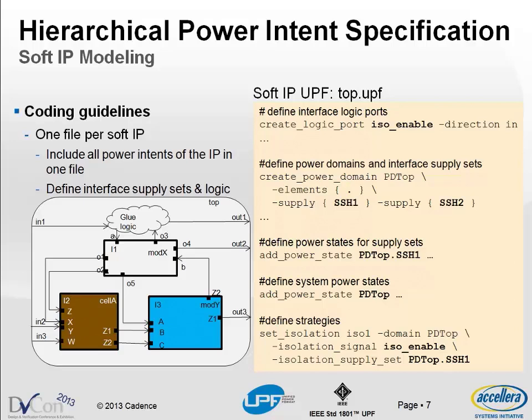And here is all abstract level. You don't have to specify all the detailed information. With those interfaces established, then you can define your power state for all the supply handles. At this point, you don't even have the detailed power VDD or VSS. But what you have is supply set or supply set handles. You can define power state.